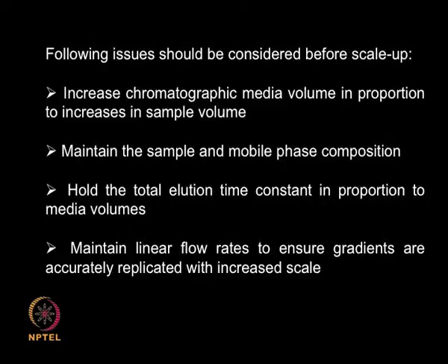We have to look at increasing the chromatographic media volume in proportion to the increase in sample volume. So if I am going to have a large sample volume, that means I need to have more chromatographic media volume, but at the same time I need to maintain the sample and the mobile phase composition the same. Then I would like to maintain the same elution time.